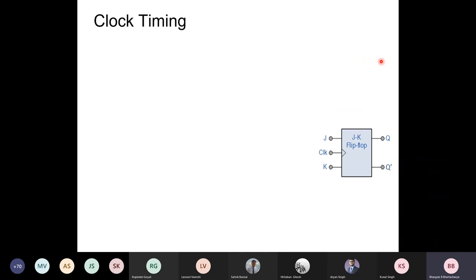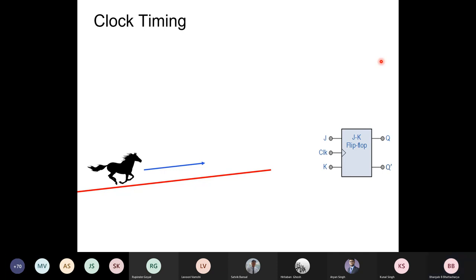Suppose you have a circuit with a combinational cloud, that means a large network of combinational circuits, gate elements, and there are several state elements like flip-flops, right? Signals are reaching the flip-flops, and the flip-flops will store the updated value when the clock makes a transition from low to high, maybe at the leading edge. Now there are many signal paths reaching the flip-flop inputs.